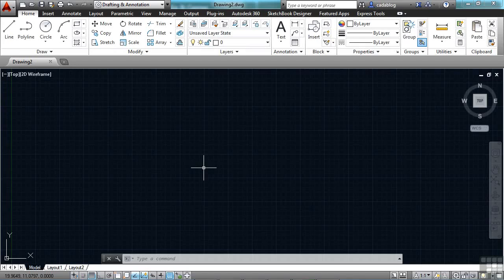Now, a new version of AutoCAD and AutoCAD LT means that there are several little enhancements that have taken place. These are small changes that will make existing tools better, even if it's just slightly, but you get enough of these things and altogether they're almost like one big giant feature all on their own. One nice thing is that you can now draw arcs in either direction by pressing the Control key to switch directions. Let me show you.